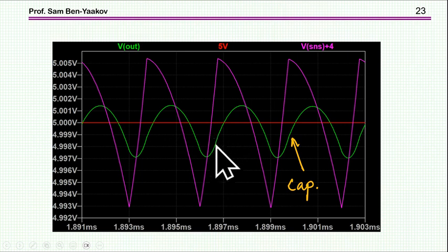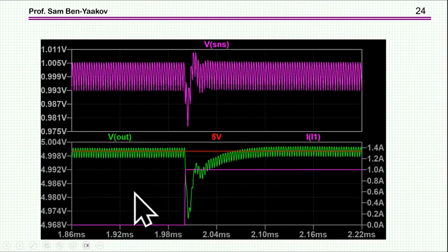So therefore, if the ripple is small, then you have to use an injection of ripple to make this circuit work. And here is the performance as a response to the 1 amp load step. Again, very nice. You see the drop in the output. It's about 25 maybe millivolts, and then the recovery. And so again, the time domain response is very nice.